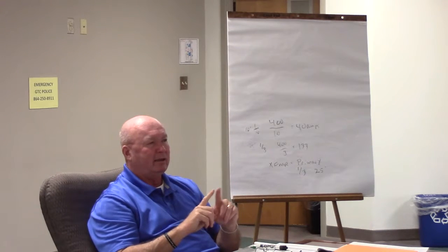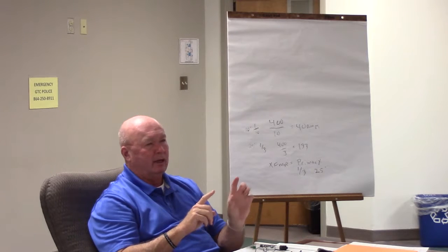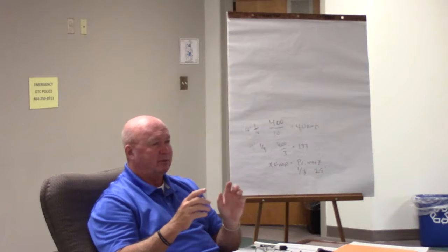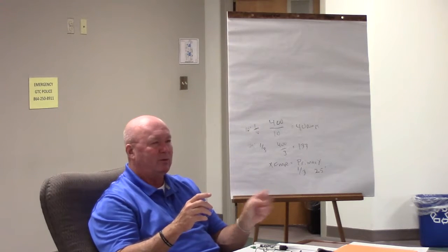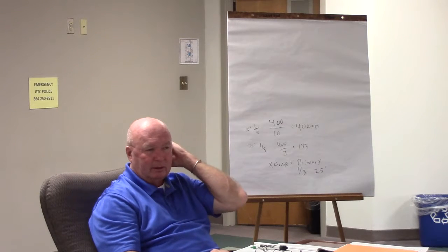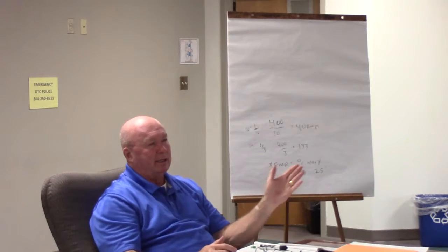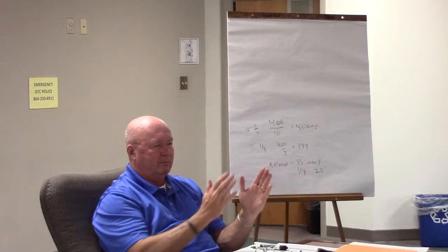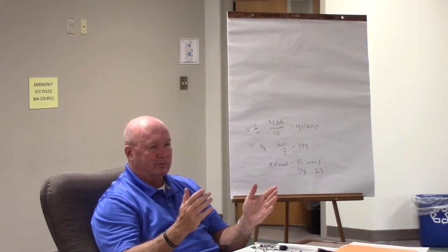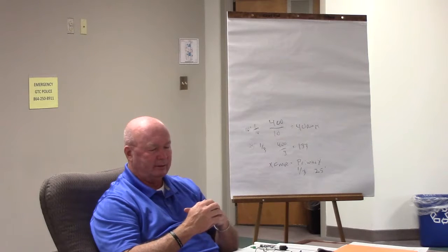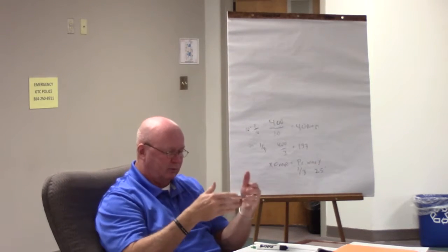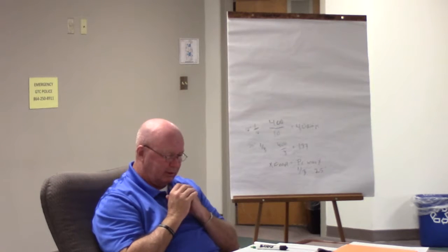Conductors, because we're counting conductors, aren't we? Not the length of the conduit, but the actual conductors, which means we have to count inside of the transformer, we have to count inside of the panels, right? Our total is 25 foot. So it gets close. But let's say, like you say, 15 foot primary, 10 foot secondary, does that put us within everything? 25 foot, right? So it puts us within it, and so we're good by that rule there. Just as a rule of thumb, just thinking in the field what we generally do.